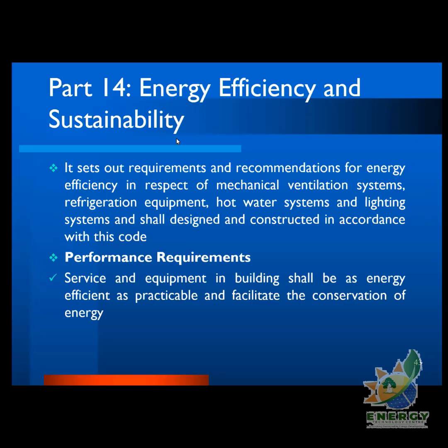Now, in terms of energy efficiency and sustainability, you have Part 14, which sets out the requirements and recommendations for energy efficiency in respect of mechanical ventilation systems, refrigeration equipment, hot water systems, and lighting systems. And these shall be designed in such a way that they meet minimum performance standards. Or if you are acquiring them, you have to make sure that they meet certain minimum performance standards.